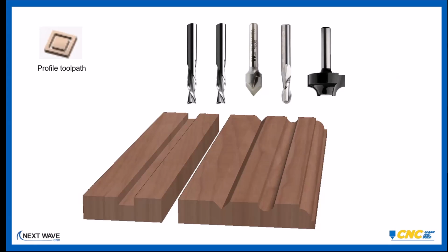You can set that bit up to cut part of the way through your material, all the way through your material, or with a profile bit, do the side of your material or something down the middle. So if you think of this as following a line, and you're either going on the line or inside or outside the line, it's pretty straightforward in its concept, and it's probably one of the big workhorse toolpaths of CNC work.